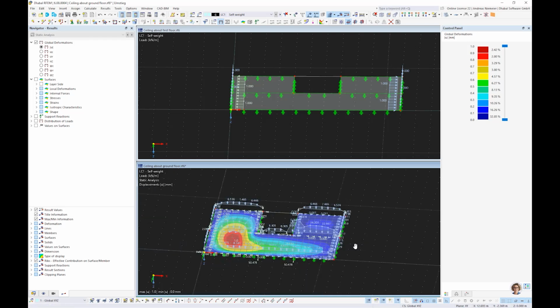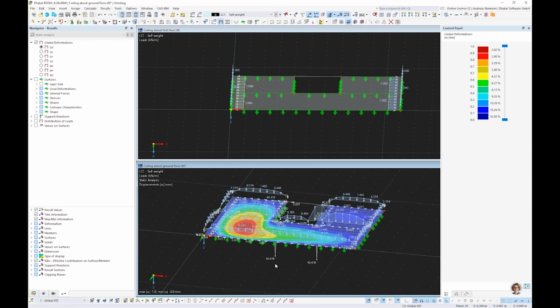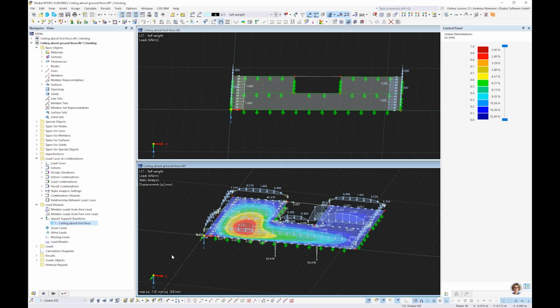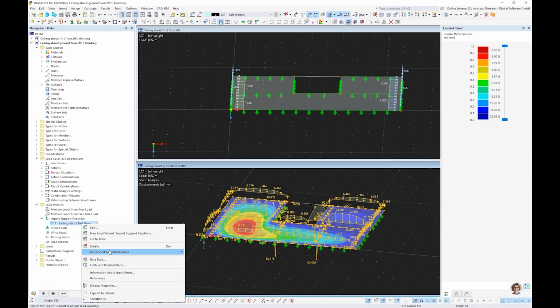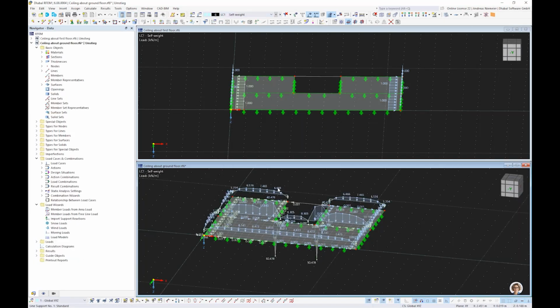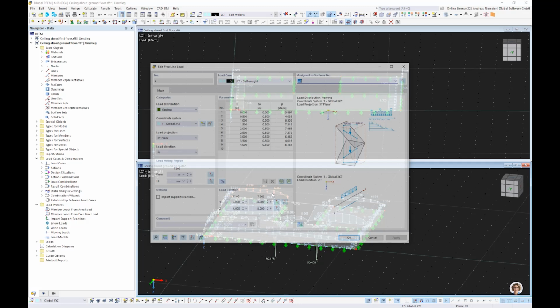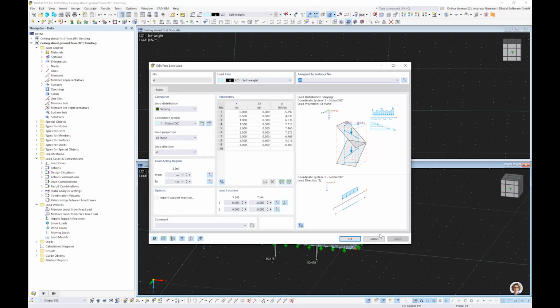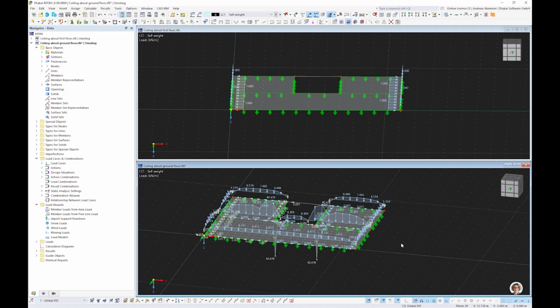Yeah? So this could be quite efficient in your work, and if you say I want to freeze something, no problem, go here to disconnect and disconnect dependent model. Then the program gives you, let's say for this load case, fixed loads which have no connection to anything. So, efficient usage of couplings. You can use update, but you can also break the update. And now let's come to the next coupling.